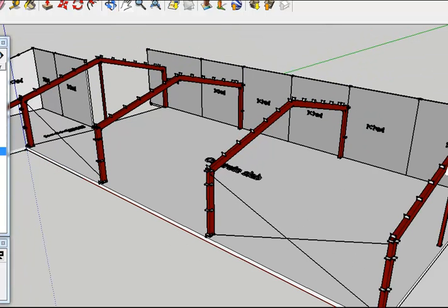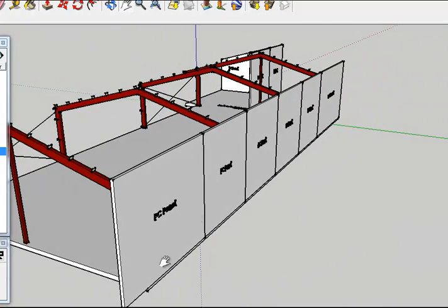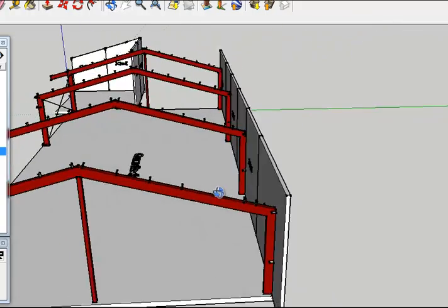Another way, of course, to brace the wall is to have these concrete panels. And these panels are very convenient because they are usually made in a factory, transported to site and craned into position. Not only do they provide a lateral or horizontal support, but they also are the structure and the cladding all in one go. And commonly the reason why we'd use a panel system like this is because we're building on or very close to the boundary, and these panels offer some fire protection.